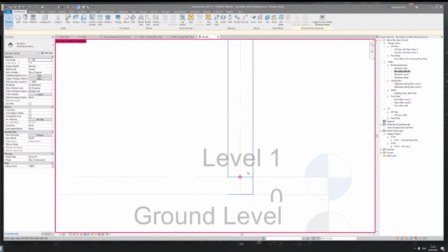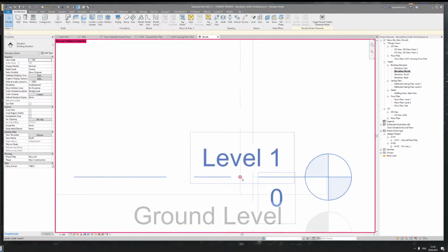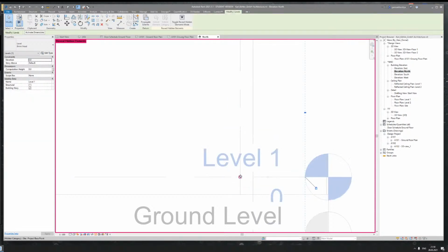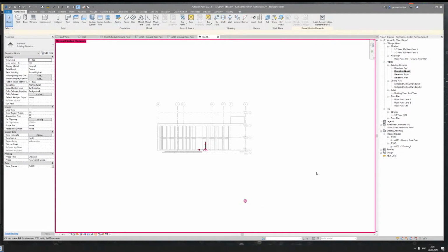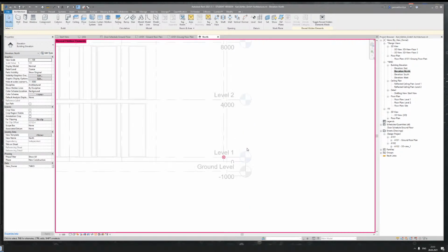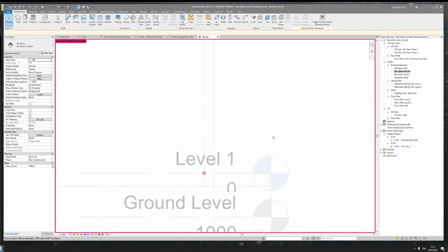As you can see, my elevation right now is mostly correct, because it's on level 1. Some people make it like that, for example, the point is here but placed somewhere here. That is also wrong, because when you load into the model the structural or engineering part, it will be flying. So you should always dimension where the base point is, for example grid A and 1, and place your base point there.